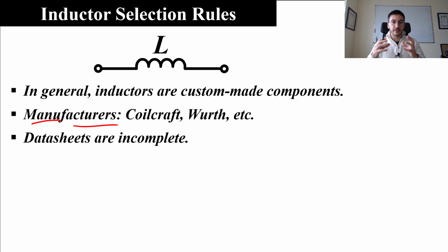So, taking into account that in this project we want a simple approach, we are going to choose an inductor from these manufacturers. The drawback of this approach is that the data sheets of these inductors are incomplete. So, for instance, we are not going to be able to evaluate core losses.